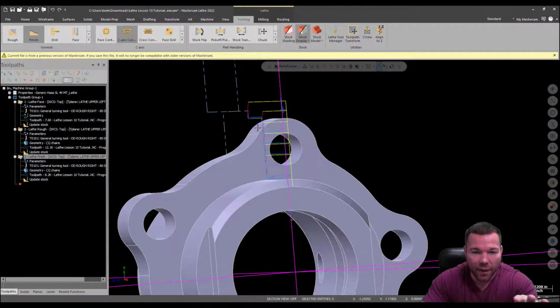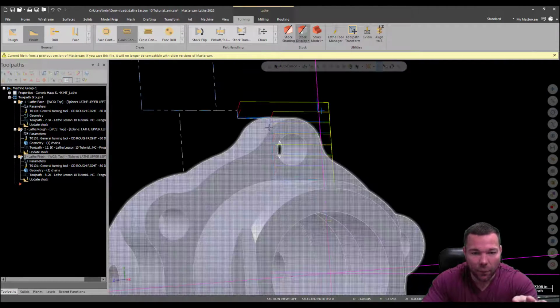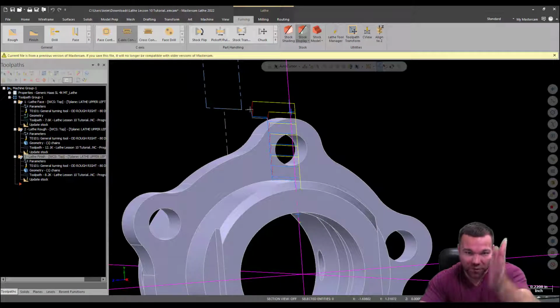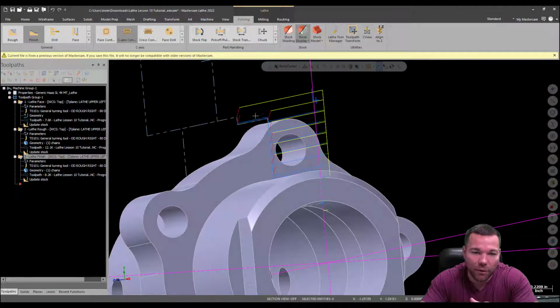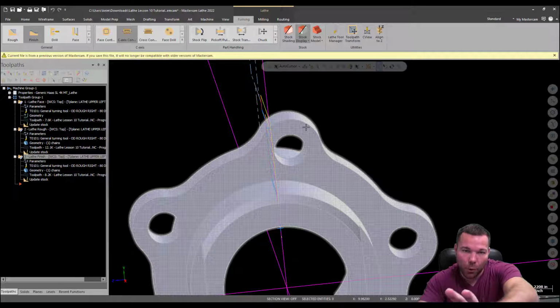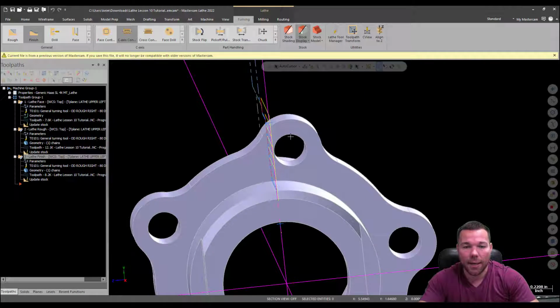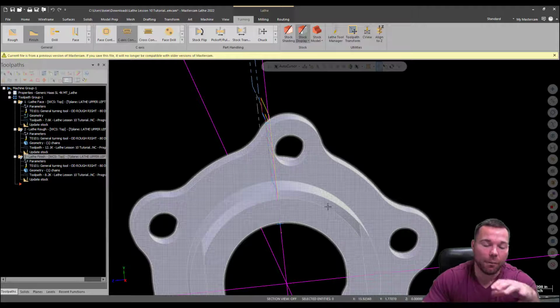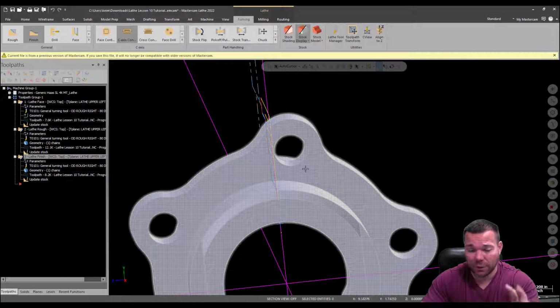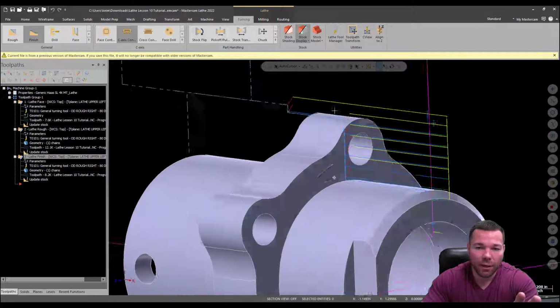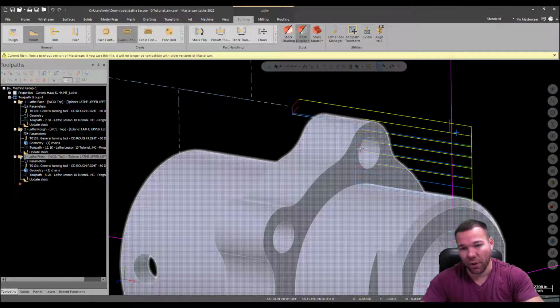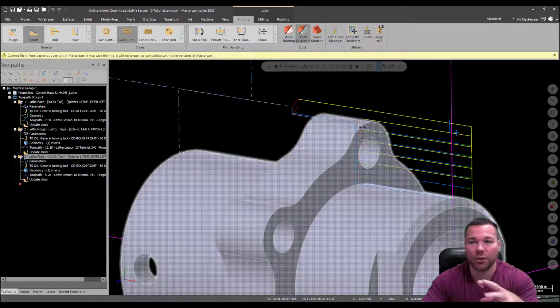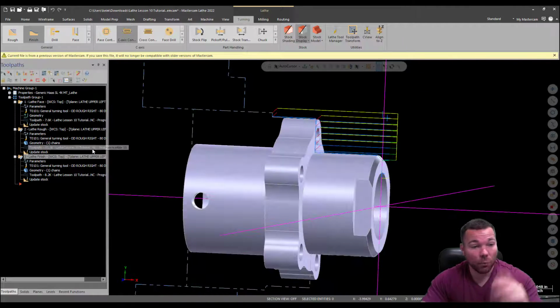And you can see here, it's not actually turning it to where it crosses the plane, like it would slice it in half. It's actually turning it to the biggest diameter. So if this part were rotated around, and this was directly vertical, it would be the outside of this. So that's actually really convenient because we don't have to rotate this part and then slice it to get that profile. It'll basically spin it and get that profile for us. So that's one of the ways.